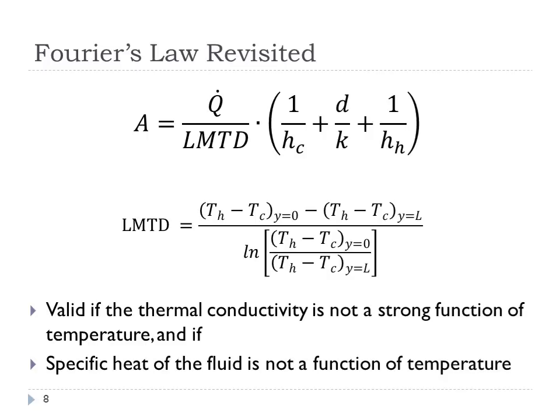So we're basically figuring out that the area is going to increase, of course, as you increase the resistance of each of those resistors. The easy one to think about is the one in the middle, the metal, like steel, which is used a lot, steel or aluminum, in heat exchangers. As you increase the thickness of the wall material separating the hot from the cold side, you're going to end up increasing the resistance and hence increasing the area of the heat exchanger.